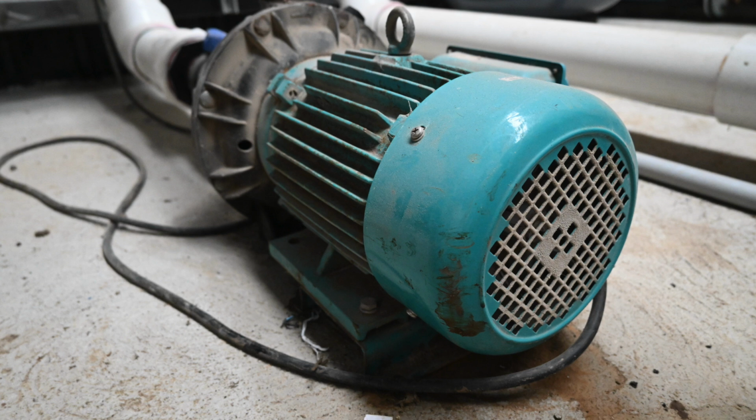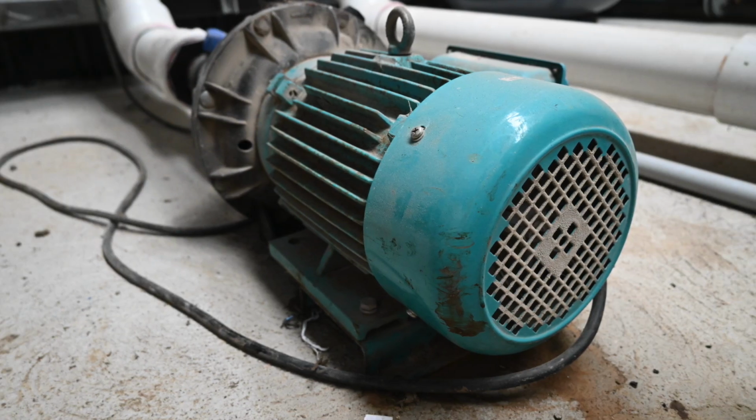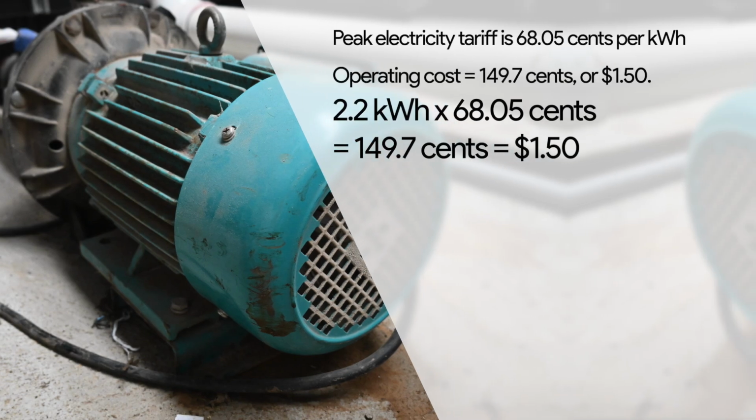Let's look at this pump. The nameplate on the motor states a power rating of 2.2 kilowatts. If this pump ran for 1 hour, it would use 2.2 kilowatt hours. That's 2.2 kilowatts times 1 hour equals 2.2 kilowatt hours. It operates when the peak tariff rate applies. The price of peak rate electricity is 68.05 cents per kilowatt hour.